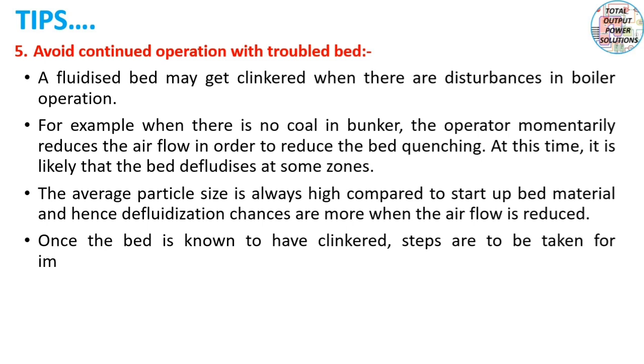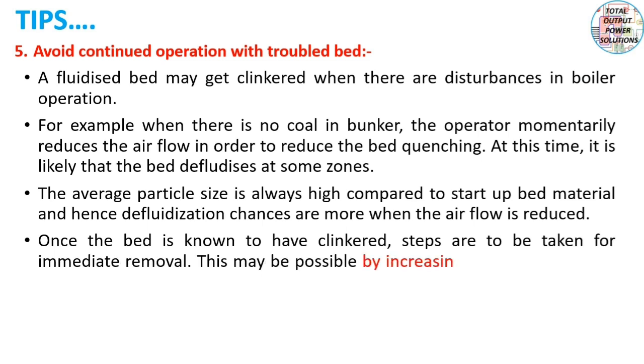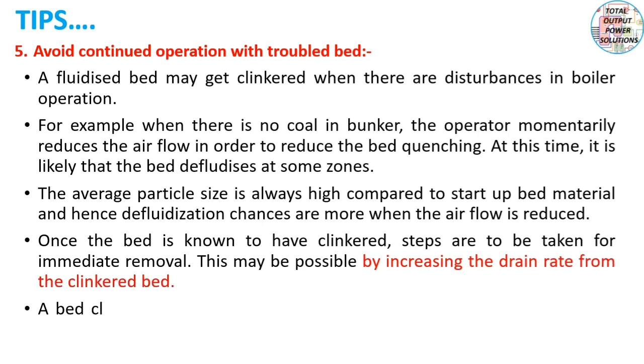This may be possible by increasing the drain rate from the clinkered bed. A bed clinkering can be figured out from the differences between the bottom and top bed temperature readings.